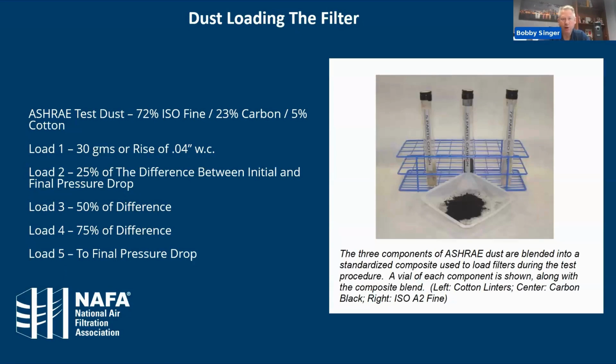Then we would run another particle removal efficiency. Then we would load to 50% of the difference between the initial pressure and the final pressure, efficiency measurement, then load to 75, and then to the final pressure drop, run our final efficiency measurement. So you're getting particle removal efficiency measurements throughout the life of that filter.